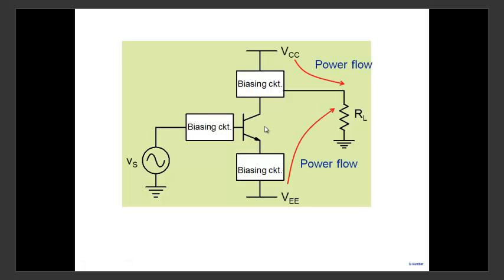And not only that, remember the amplifier amplifies the signal which is connected to it. And the whole purpose of amplification is to obtain power which is delivered to the load. And so the supply and the biasing circuit and all that you see here is not only there to push the amplifier into the forward active mode, but also to supply the power.